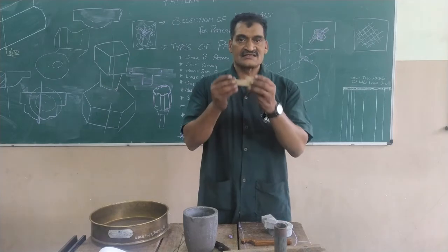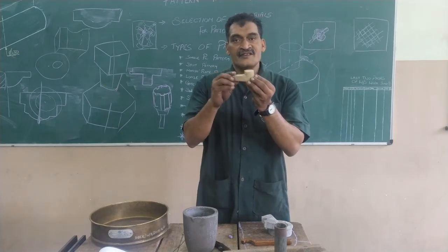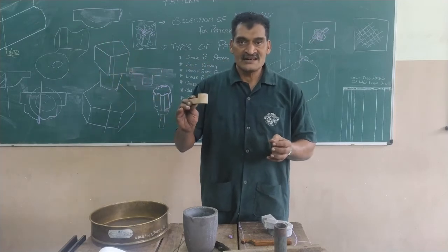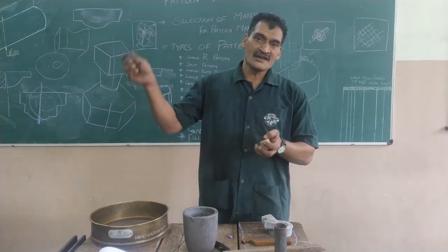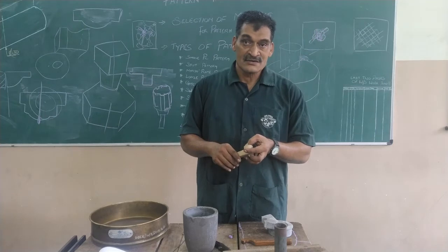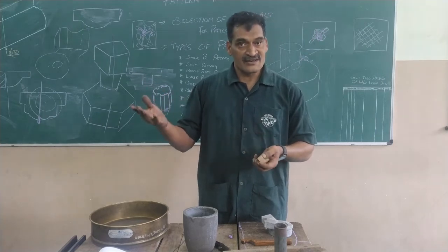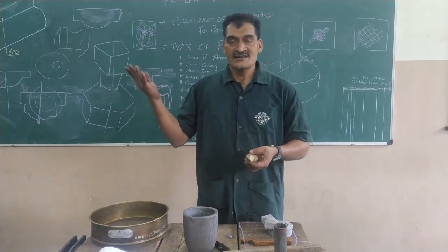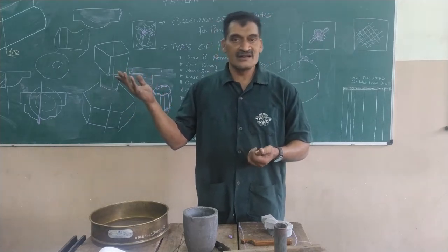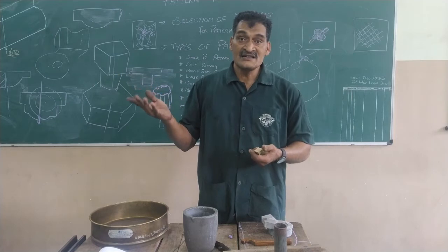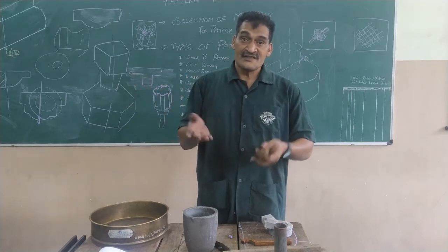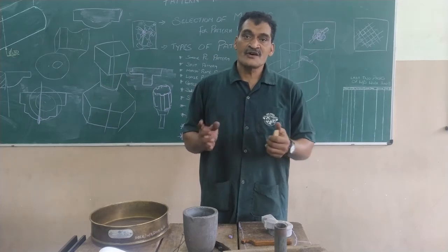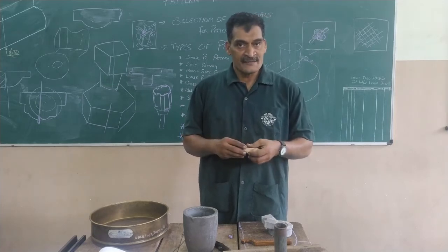Suppose we make this pattern, we make a mold in sand of this n number of molds, and then we will be pouring molten metal. Molten metal, the temperature is hot. Of course, it will be roughly around 700 to 1200 degrees C, which is very high. As a result of which, we could get burnt. So to prevent that, we got to have proper PPE.